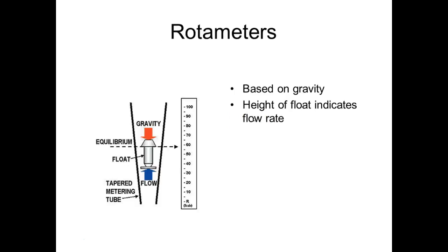These are rotameters. Basically they work off of pressure too. So we put flow through the thing, it tapers down, right? You understand? The flow changes, and then this thing right here would just rise up with gravity, and then you could read it off the side or have some type of unit over here that would convert this. So this could be a magnet, right? And then we could have Hall effect sensors out here, right? Or it could just be this and then you just convert to a dial. Are we okay?